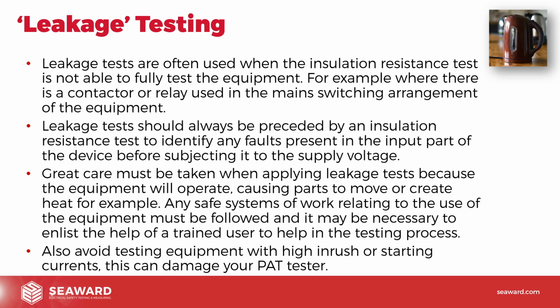Now, the poor old PAT tester is rated to cope with certain amounts of inrush currents. But if you're doing that all day, doing 100 of those all day, don't be surprised when the relays burn out or the fuses start blowing, or you test a big piece of equipment. So always think about what level of current is going to be drawn by this thing, because it's got to go through the PAT tester. Normally, it's fine. You've got it plugged into the mains. Great. No problem at all. It draws a bit of extra current from the mains. That's okay. But when you're pulling that through the PAT tester, it's only rated for certain levels of current.